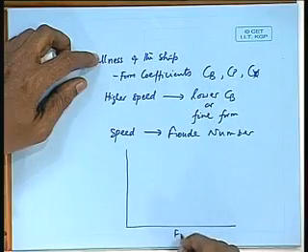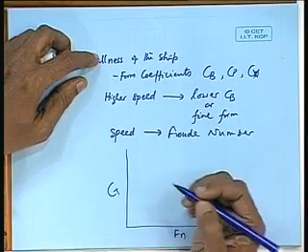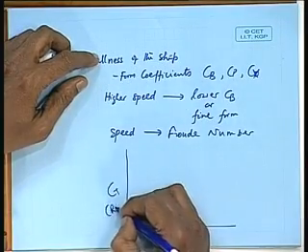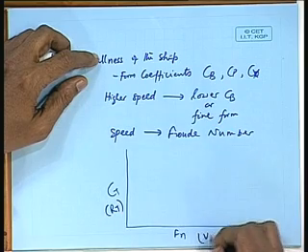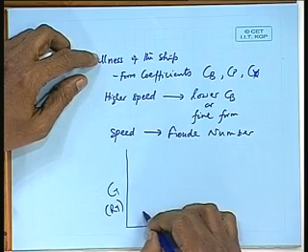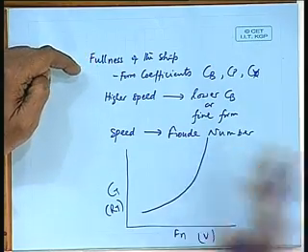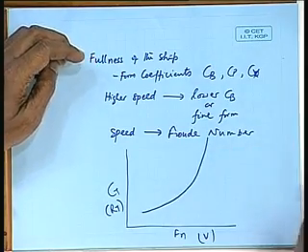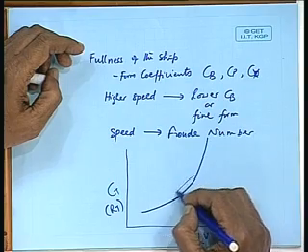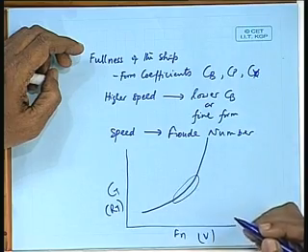Say this is Froude number, this is CT, or we can also draw RT versus speed for that length. How will the curve be? We have seen the resistance curve goes, wave making resistance at a higher speed becomes more prominent, and it varies to the power of 6. So, somewhere after this speed, somewhere around this speed is my optimum speed.